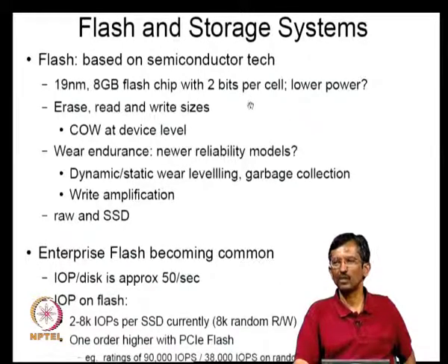but it has more errors. So you need a good amount of error coding for it. Reed-Solomon coding or other types of coding are also being used. For example, you might have some XORs, some parities horizontal, some parities vertical, all kinds of things people are designing. You can have RAID also on top of these things. So many designs are coming out. One thing about this also is that it has a potential of being lower power.